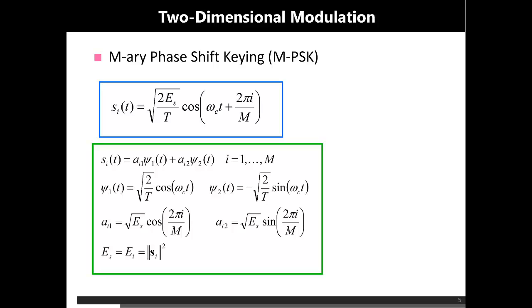Before going into the mathematics, let us discuss the main concept behind phase shift keying. As amplitude shift keying is the counterpart of amplitude modulation, similarly phase shift keying is the sister modulation scheme in digital communication, as compared to the phase modulation used in analog communication. The main concept is to change the phase of the carrier in accordance with the amplitude of the message signals. Since we are in the digital domain, the message symbols are digital and only finite in number. So the carrier will experience a phase change in accordance with each of the transmitted symbols.